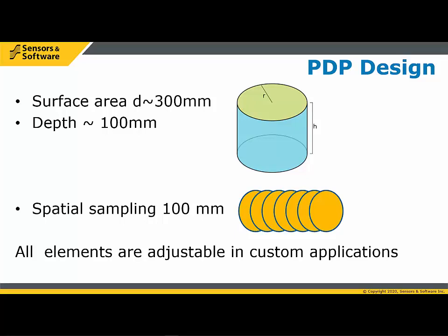If there's a demand to make a real-time map where you go out and do 10 lines and then convert them to a map right in the device, that can be done fairly easily because we do it now. But it hasn't been an application that we approach that way. So we treat each line as an independent line, then we put it into a software package that essentially does the gridding or the interpolation and builds up the gridded data set from which the color map or contour map is generated.